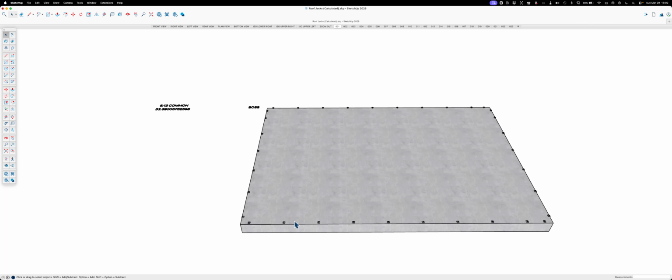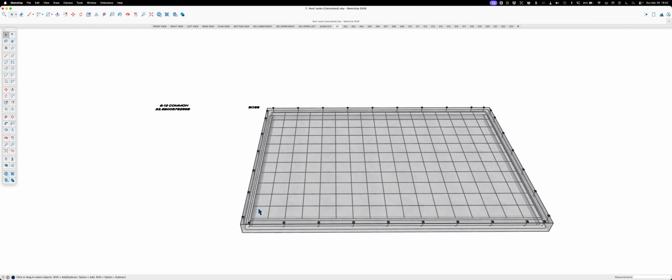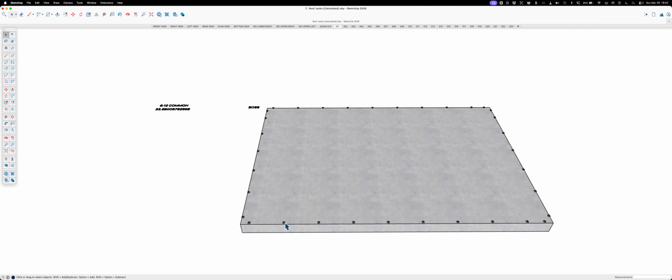It's amazing. You pick all the stuff you want. I wanted 24 by 24, number 3 rebar back and forth, 2 bars bottom, 2 bars top, and anchor bolts set every 4 feet because that's just where I live. But anyways, let's go through this and show you how animation works too, like the scenes.